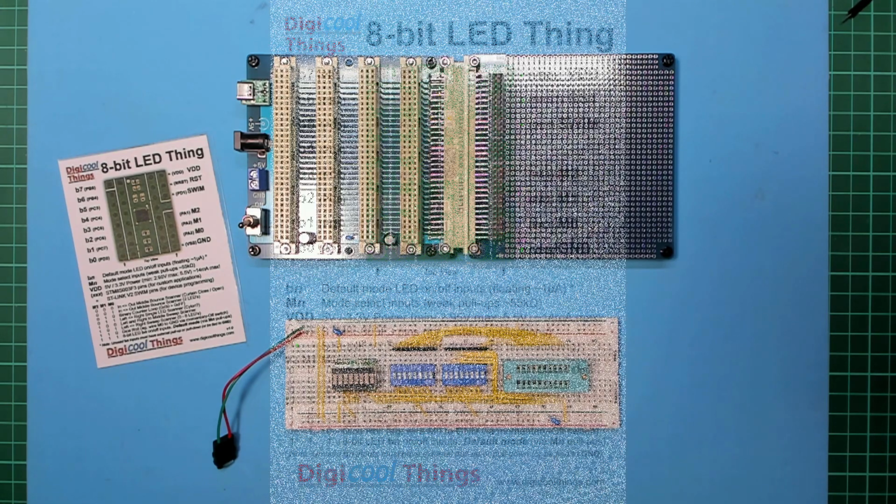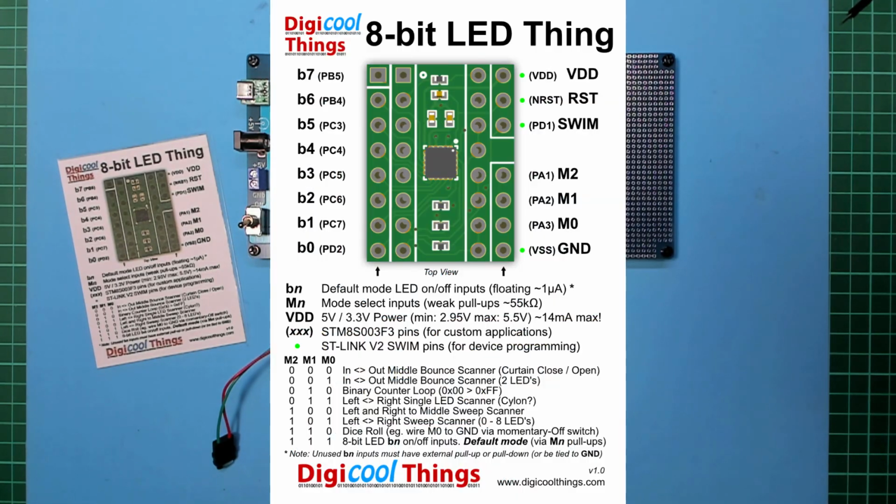In case you hadn't seen my 8-bit LED thing before, it is a little DIP module I made several years ago mainly for my experimenting with digital breadboard projects. It does a number of fun pre-programmed actions via 3 mode select inputs, but in its simplest intended use, it enables monitoring 8 digital lines with virtually no signal load, about 1 microamp, using either 3.3 volt or 5 volt power. Total power usage, even with all 8 LEDs illuminated, is only a maximum of about 14 milliamps.